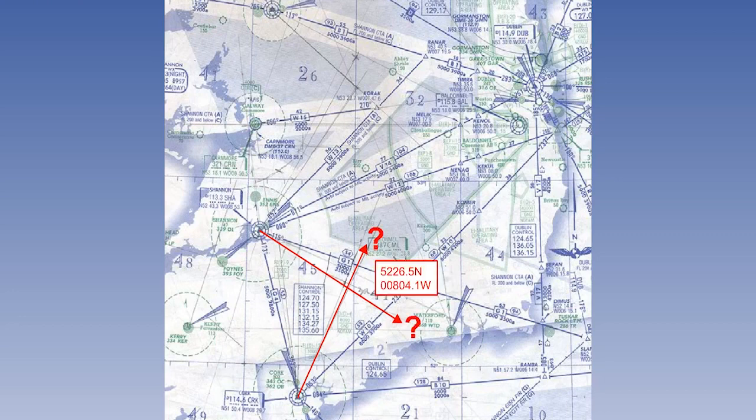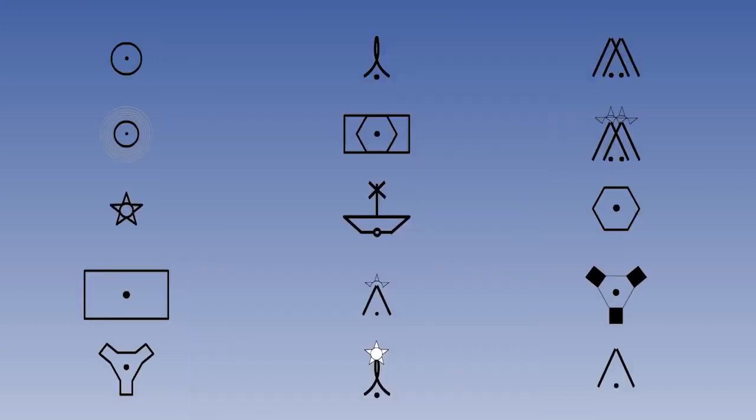Sometimes the question is asked in reverse. You are given a position in latitude and longitude and asked to select the correct 2 radials. You will need to know your basic cartographic symbols. You will become familiar with these and other types of question as you try the practice questions associated with this lesson. However, although it is usually easy to understand what is wanted, sometimes the difference between a right and wrong answer is only 2 degrees. It is essential to plot accurately.